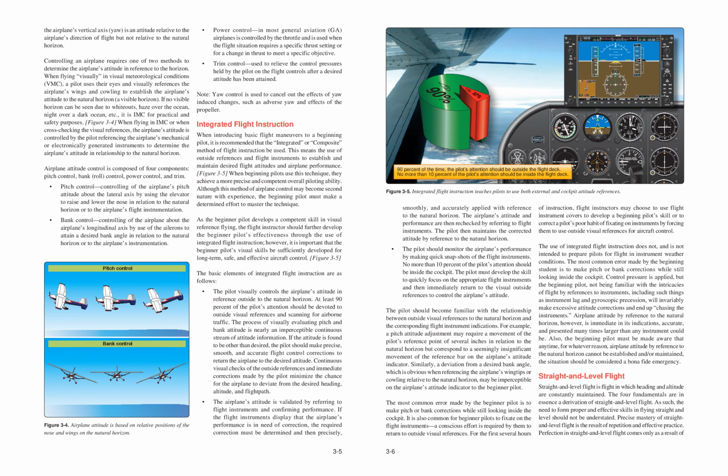90% of the time, the pilot's attention should be outside the flight deck. No more than 10% of the pilot's attention should be inside the flight deck. Figure 3.5. Integrated flight instruction teaches pilots to use both external and cockpit attitude references.